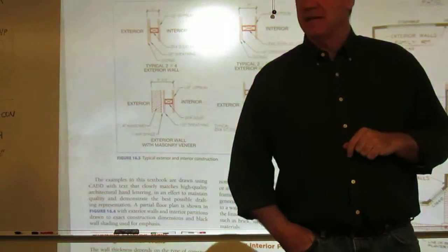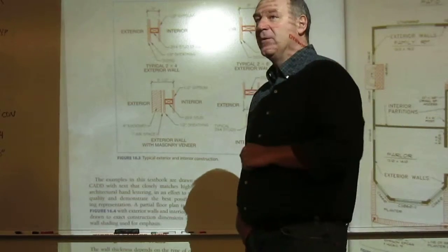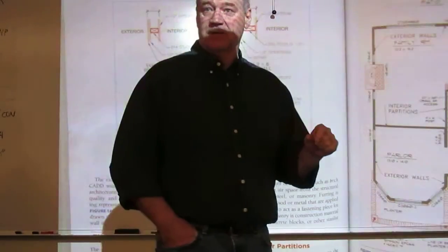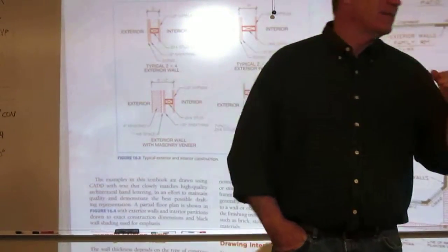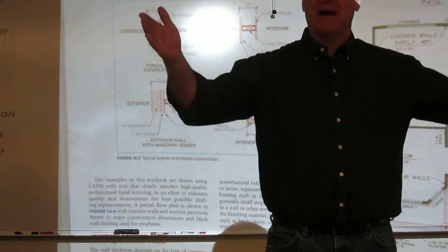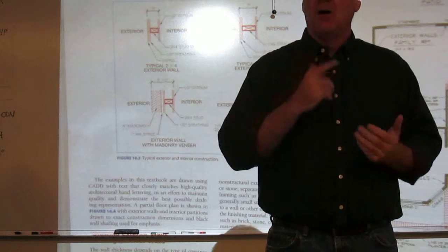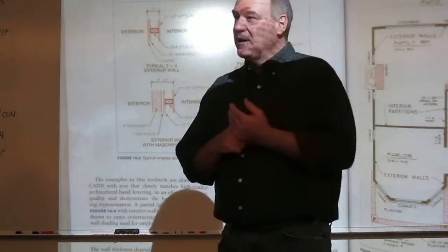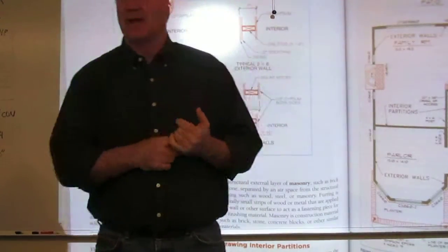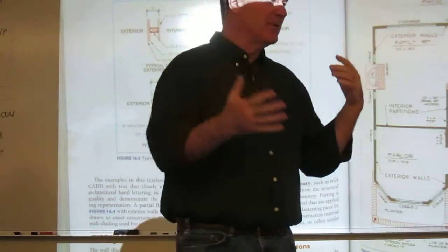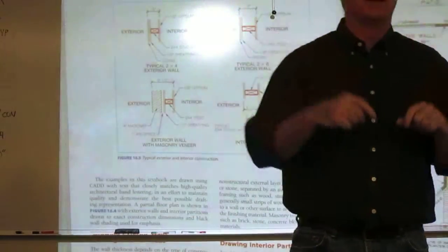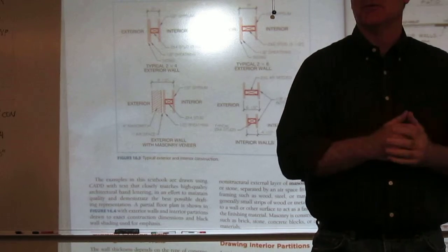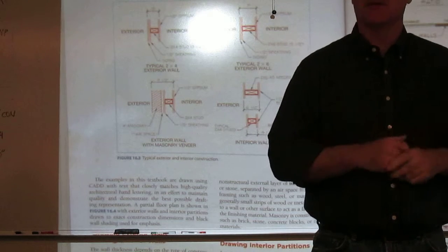Now, one of our mandates when we draft is we always show the object in the finished condition, right? I don't know if you remember this. Back in 131 through 135, we talked about this and said, always show the part in the finished condition. And around the 90s, we quit telling these craftsmen how to build stuff, right? Remember the abbreviations? We now use depth, and I don't say drill this or ream this because I'm not the construction specialist, right? We leave that up to the craftsman involved.